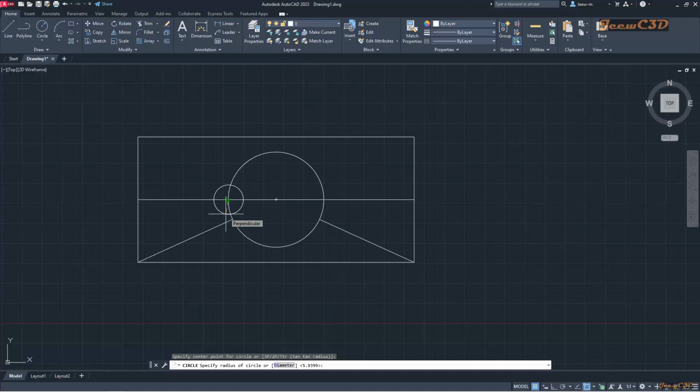It is now snapping to a line. So you need to make sure it is not snapping to another line before finishing. Now if you click here, it will snap to a perpendicular line, but if you move further away, it will not snap. Now I can stop the command. I will click here. I will do the same to this side. To initiate that one, I will press space bar and I click here. Now it is the perpendicular one. I press tab, and tab once again. Now it is the intersection. So I have another circle here.